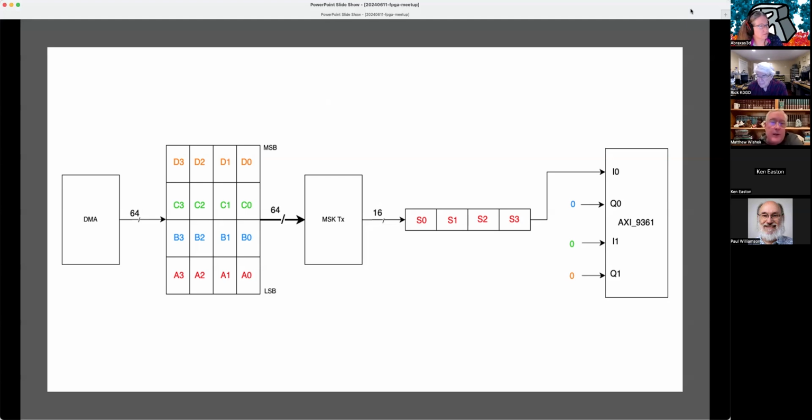there's a shift register, or a multiplexer, to take each bit in order from the LSB to the MSB. And then it does the modulation, and then we're putting out 16-bit samples now. It was 12 previously, but I may still make it 12. But the resources aren't that critical if we're using the DSP slices.